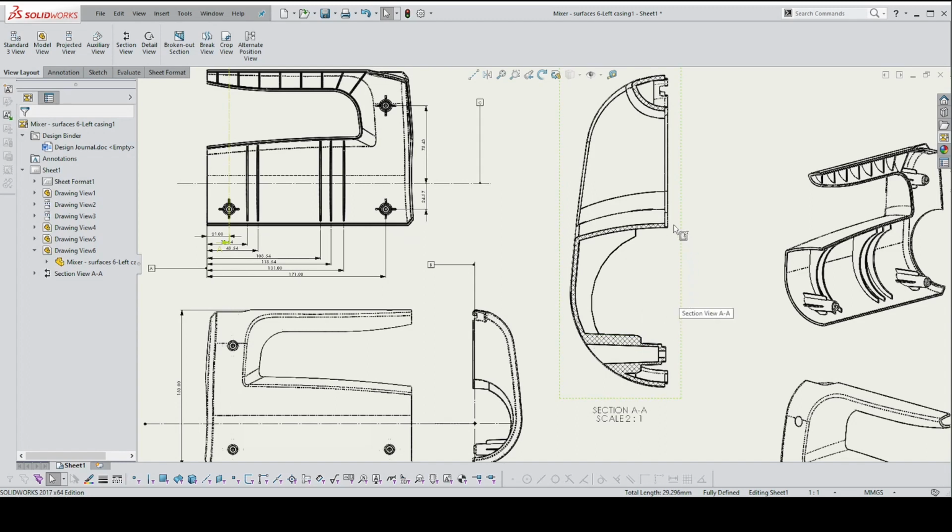But in this view, I can now figure out all of the size dimensions, and that's where I'm going to put all of my size dimensions. So if I see that you are concerned about putting position dimensions in one view and then size dimensions enlarged in another view, that's going to get you good points.